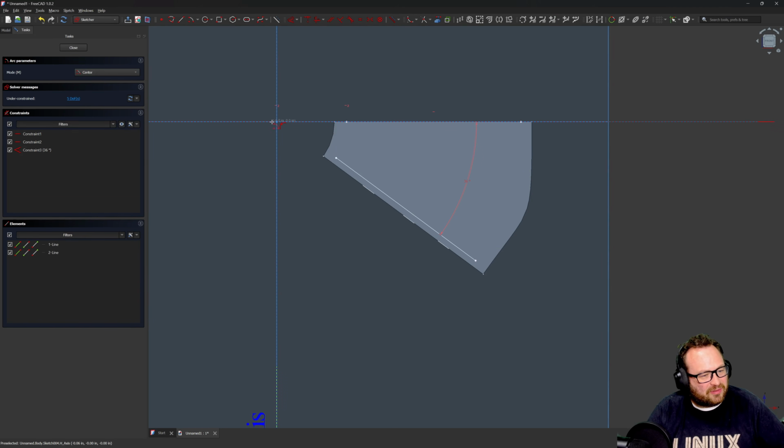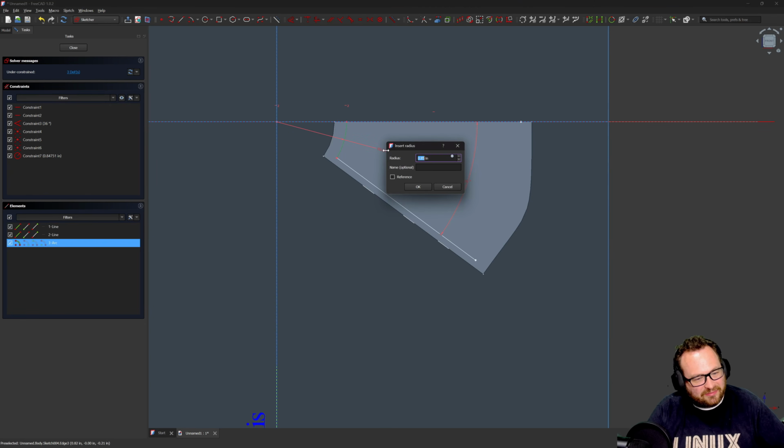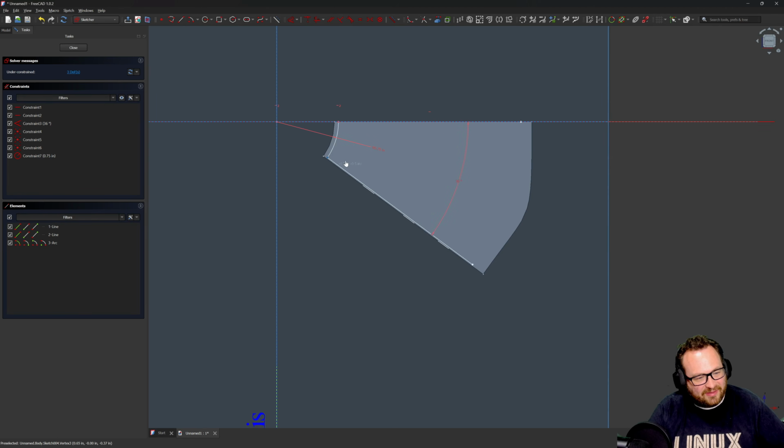I'm going to make an arc, right? We'll start from our origin there, and then from there to there. I can make a radius of 0.75. Again, lying comfortably within that surface. And then where does this line end up? Well, I want this line coincident with the origin, so I'll select this line, hit C for coincident, and select my origin. Again, I don't know if that went, so there you go, hit the C on the keyboard, there's your line, there's the origin, and there it snapped, right?